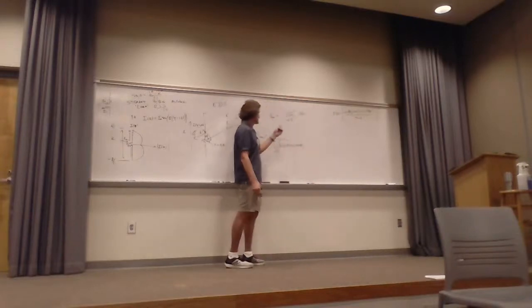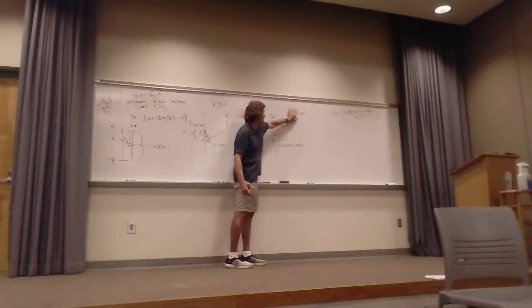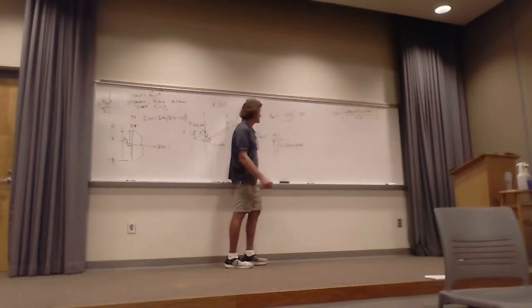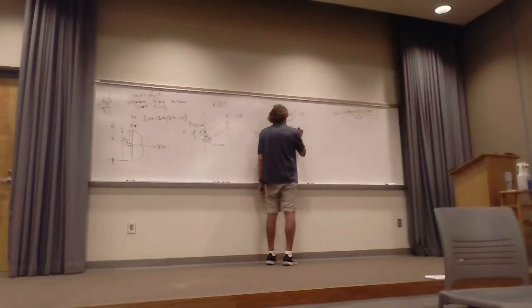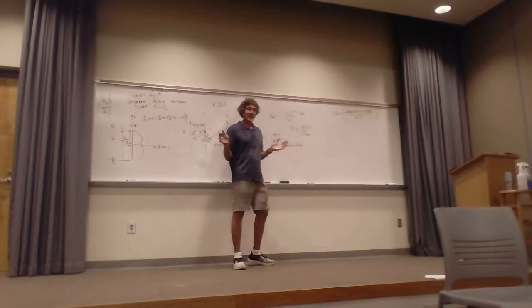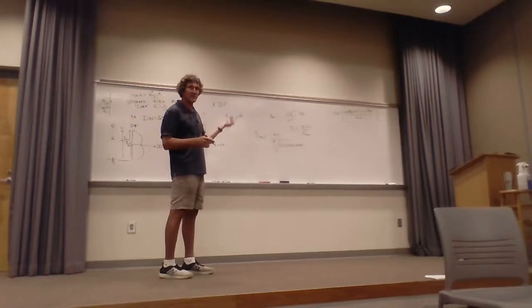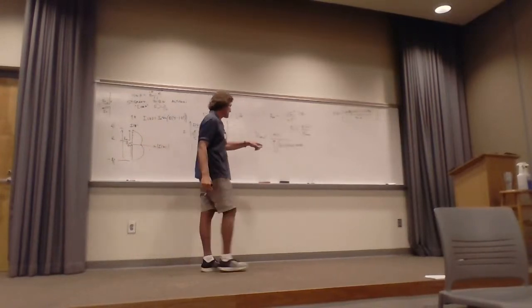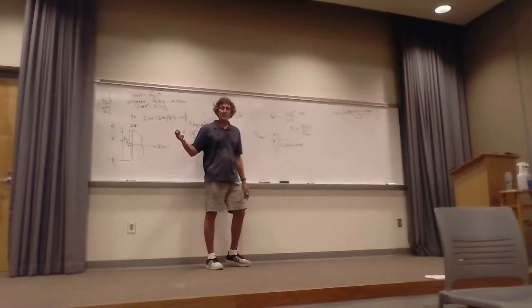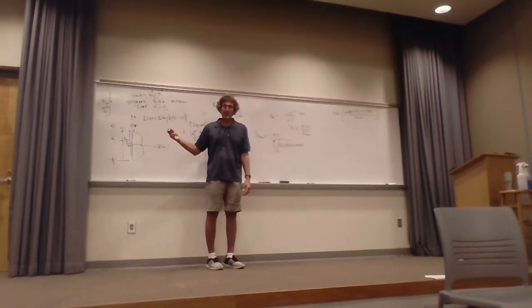Because when you look at the power density, we want it normalized. All that stuff there doesn't matter. The only thing that matters is F theta. So the normalized power density would be F of theta over F max, which you don't know. So each time you have one of these, you've got to calculate F max first, then divide it into F theta, and then you'll have the normalized power density. Then you do this to calculate the gain, but don't worry about that. I'm not going to ask you to do that. There are no shortcuts to a lot of this, unfortunately.